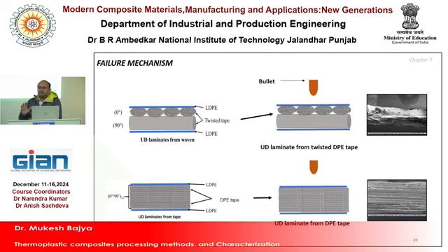So we have not changed the material, and we have not changed the processing temperature; we have only changed the structural form, and we are getting positive results. So in composite formation, each and every step is important: structural form, preform, preparation, everything. You need to take care while designing any composite for your desired applications, whatever applications you are planning.